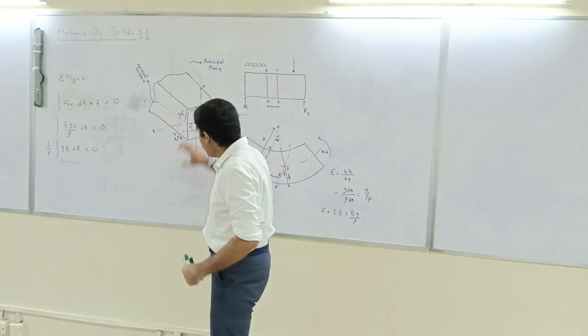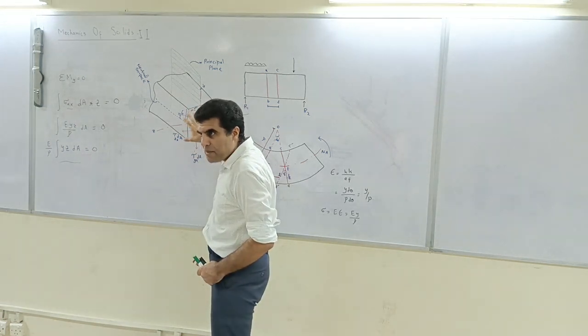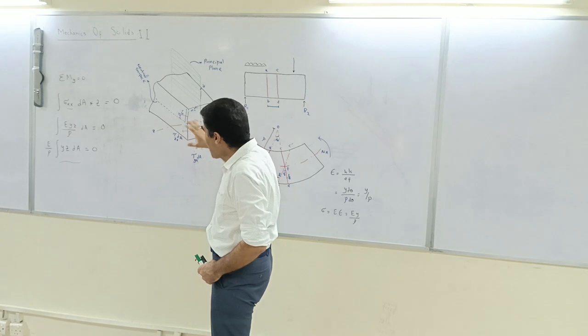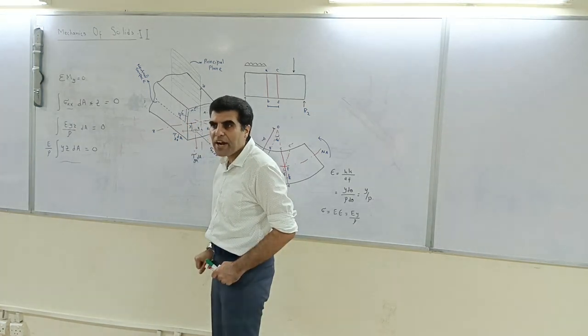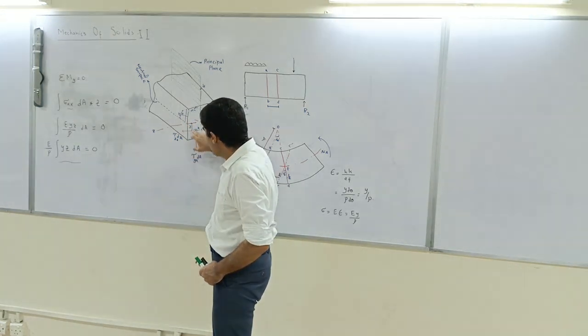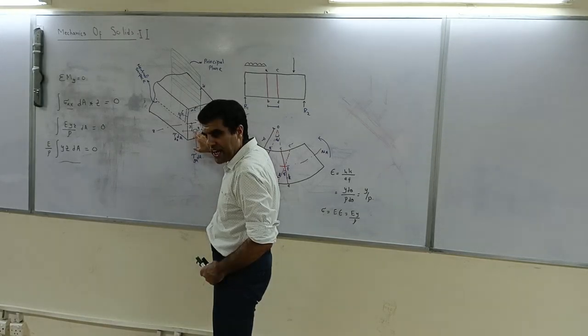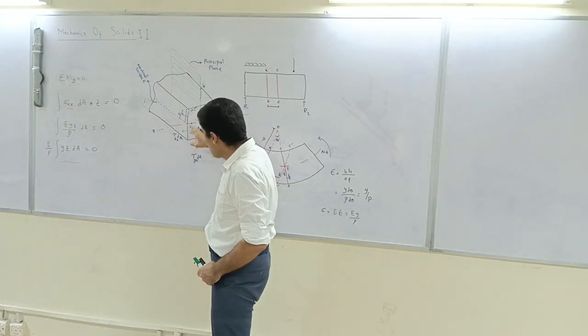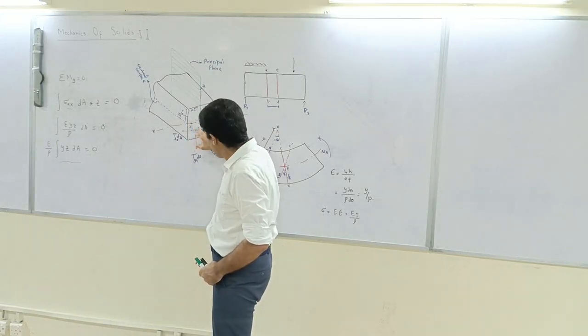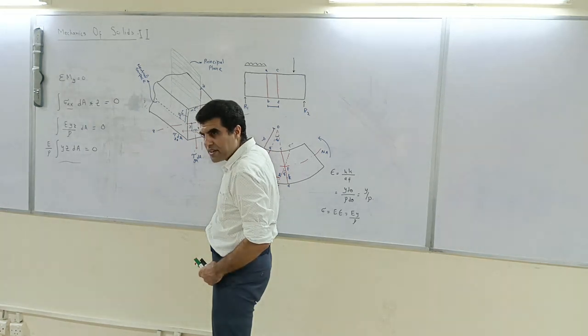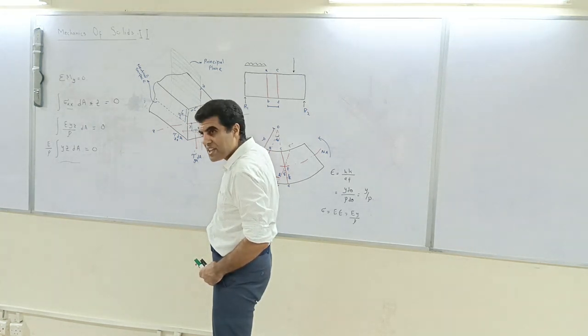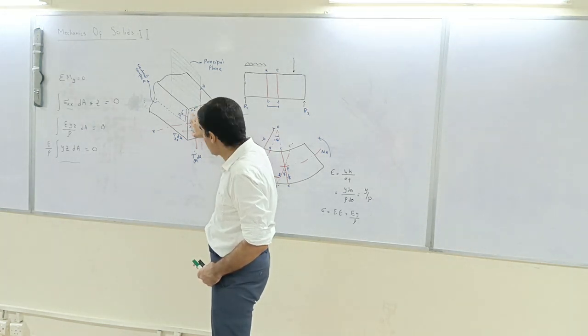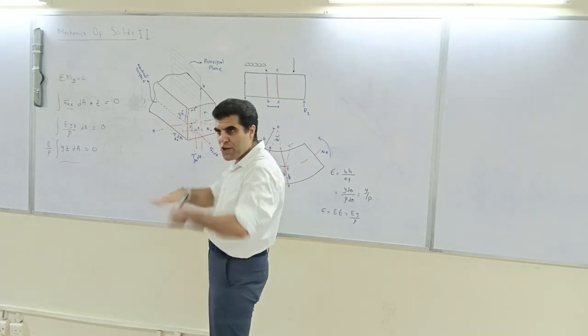In the case of the rectangular beam, you can see that by default this is satisfied. You take a small area, multiply it with yz, and you can find a mirror area over here, over there, and over there, add them up and you get 0.